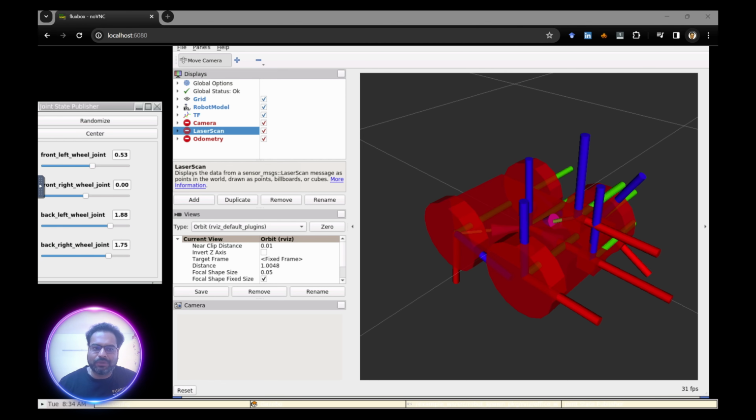I hope it was useful and you have a decent understanding of what a URDF is and how to spawn a robot from a URDF inside Gazebo and Rviz, which are typical tools that we use when we are building simulations for robots. And if you have some custom robots, so if you are an expert in SolidWorks, for example, you could design your own custom robot, export it from there, follow the same procedure, and import and spawn it here.